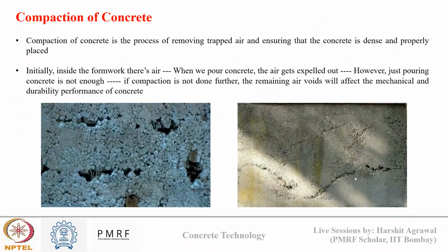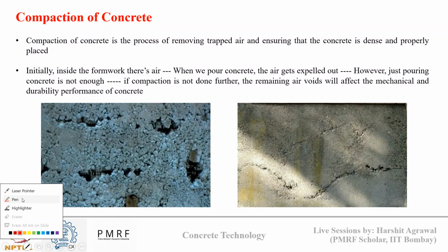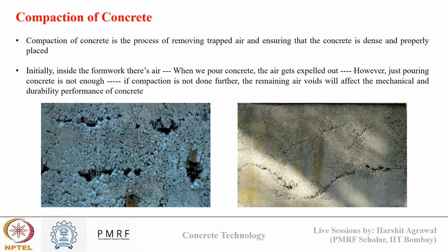So now, after mixing, transportation, and pumping of concrete inside the formwork, the next step, and often the most important step, is the compaction of concrete. So what is compaction? Compaction is a process of removal of trapped air and ensuring that the concrete is dense and properly placed.